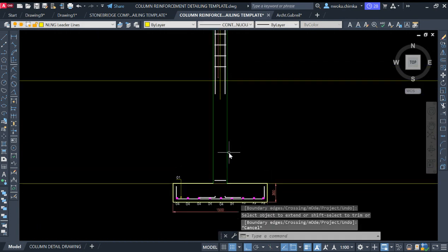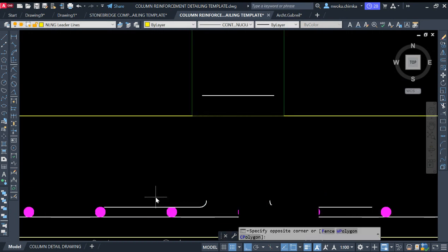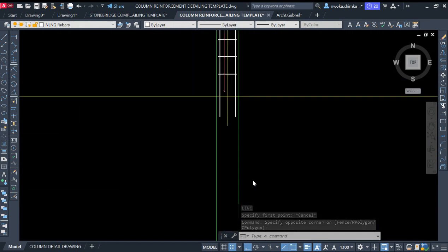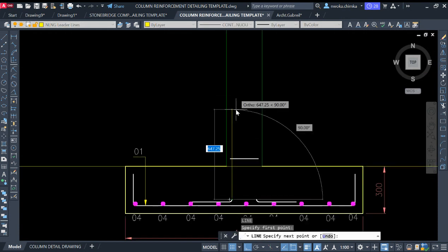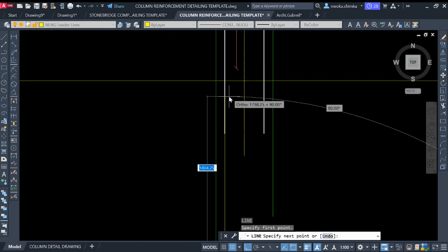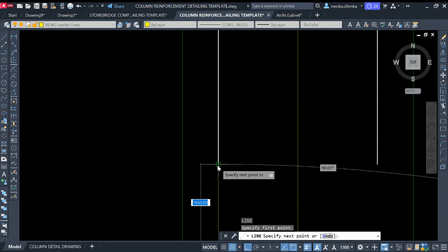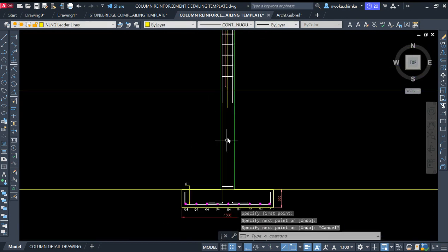Then I will have to create another one again. We already have this column anchor here, but this is for the setup. This is called a lapping reinforcement from the foundation with the column. So I'll show the connection between the foundation and the column, which is called a starter bar. I'll click on this place, offset, and bring out a line from this point first to this DPC. On reaching this point, they want to touch and lap each other, so I'll just drop it there.